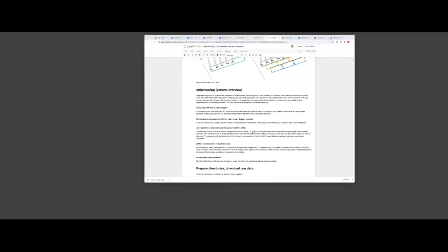That co-registration in this application is done based on geometry first. So this works with most of the SAR platforms which have precise orbits. Don't expect it to work, for example, with RadarSat-1, but most of the other sensors, ERS, Envisat, ALOS, Sentinel-1, COSMO-SkyMed, TerraSAR-X, everything should work with this method.